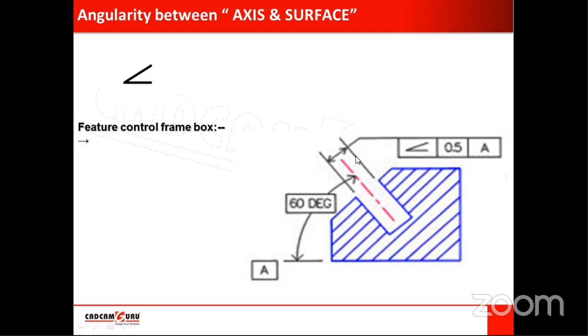If you want to speak here, if you see, there is only one direction of deviation. Means there should be linear direction of deviation. But if you see in assembly point of view, if you try to assemble any pin or any cylindrical component inside this, if it is deviated in this direction, perpendicular to the screen, then also there will be difficulty for fitment, right? So it is okay if you mention linear deviation, but for proper fitment, some people may expect circular zone